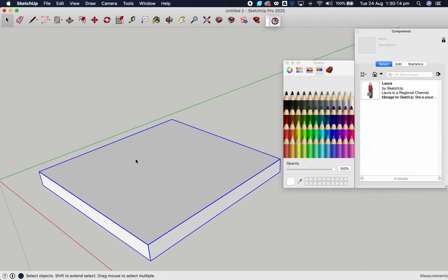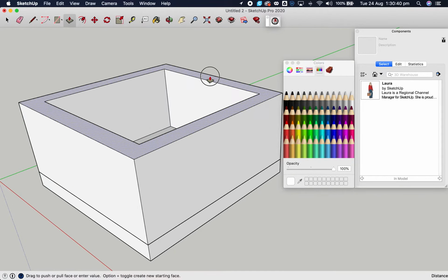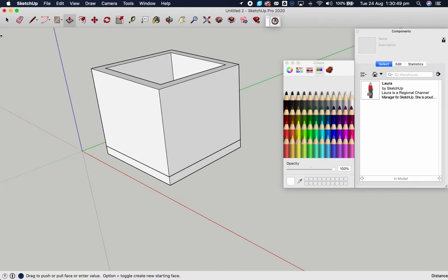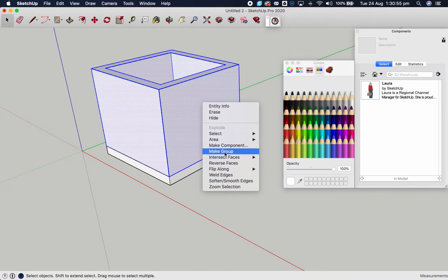Okay, so next up we're going to go into here and we just don't go into the group. We go to the edge tool and we click on the edge. No, that doesn't work. We need to go over and we need to create a new shape. And then we go to the edge, as you know, and we type in 300, which is the thickness of an external wall. So we're going to bring this up by 2700, press return. Okay, so this is our wall, and obviously we need to triple click on this wall and we need to make it as a group.